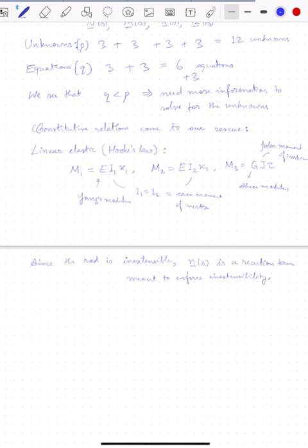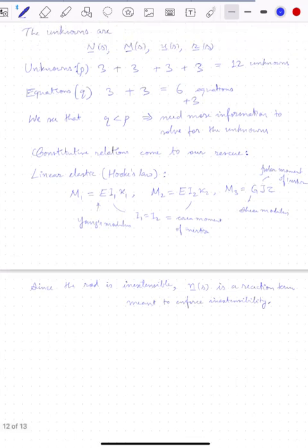So here, depending on the situation, if it's inextensible, then we will have some requirements on R prime. What we see is that the norm of R prime of S is equal to 1. So we are enforcing one constraint from here as well. And the second is that R prime of S dot D1 of S is 0. Likewise, R prime of S dot D2 of S is also 0.